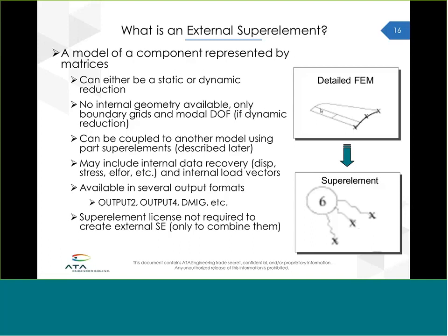And what Nastran will do, it'll write what are called data recovery matrices, so that once you have this reduced superelement, it can recover for you what that torque is based on the deflection and loads going into these boundaries. So by using an external superelement, it's not that everything inside is opaque anymore. You can still use data recovery matrices to get those out.